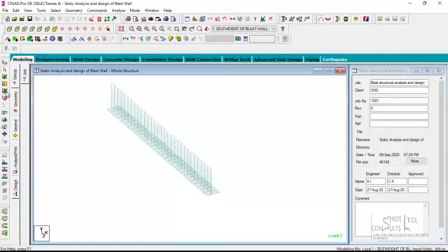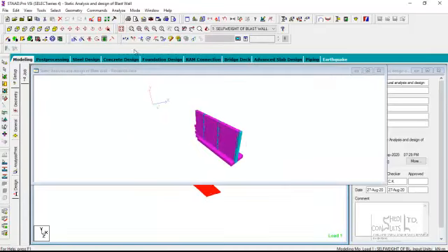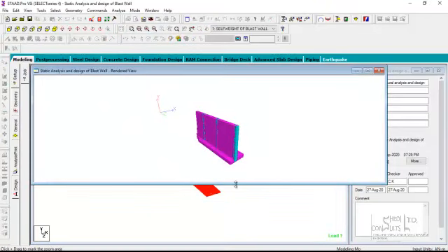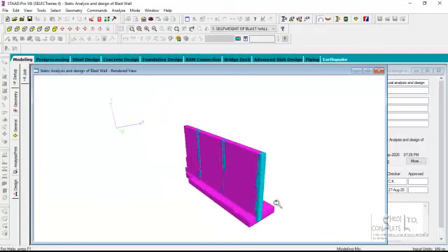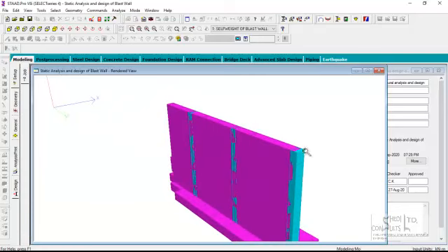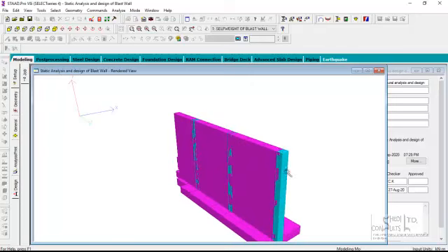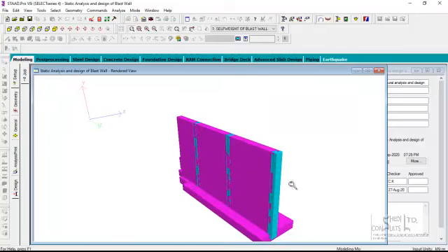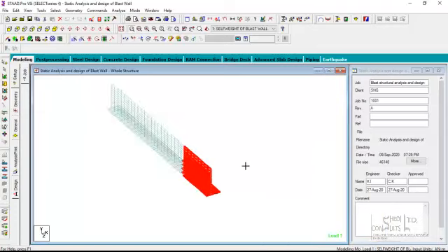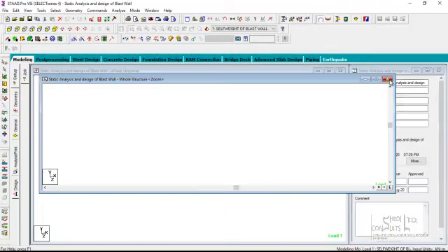If you look at the representation of the blast wall and look at the columns, you see that the column's position is such that the longer side has its maximum moment of inertia about its major principal axis, higher than its minimum moment. So in the event of an explosion, it has more moment resistance against plastic failure.